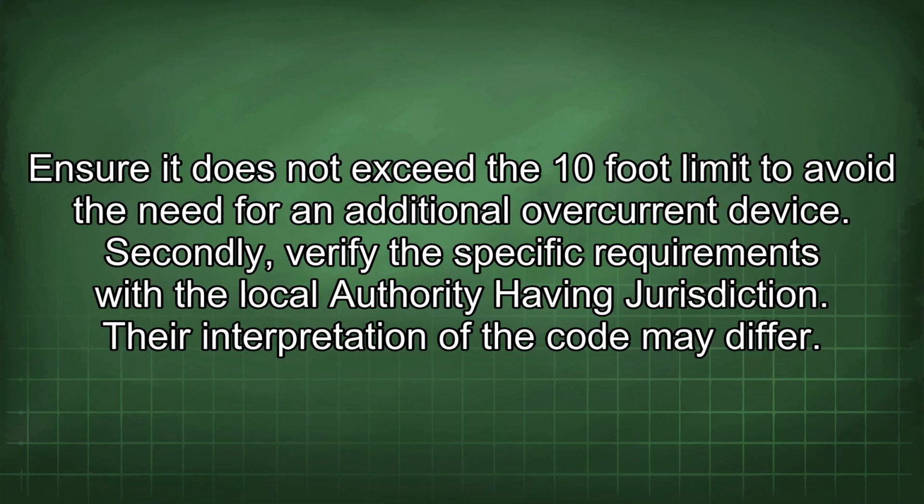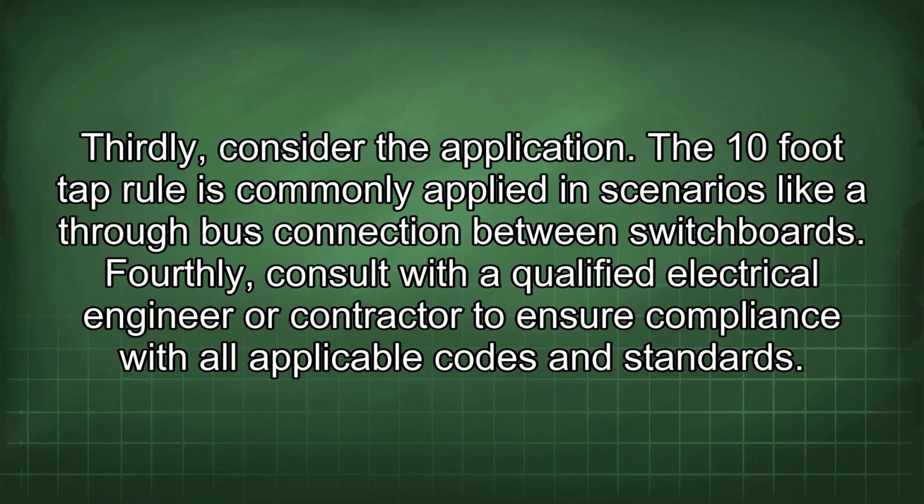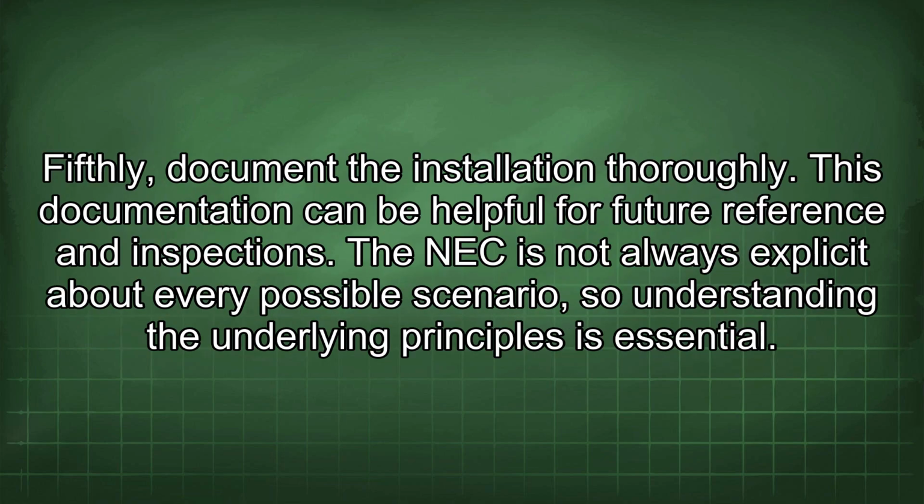Secondly, verify the specific requirements with the local authority having jurisdiction. Their interpretation of the code may differ. Thirdly, consider the application. The 10-foot tap rule is commonly applied in scenarios like a through-bus connection between switchboards. Fourthly, consult with a qualified electrical engineer or contractor to ensure compliance with all applicable codes and standards. Fifthly, document the installation thoroughly. This documentation can be helpful for future reference and inspections.